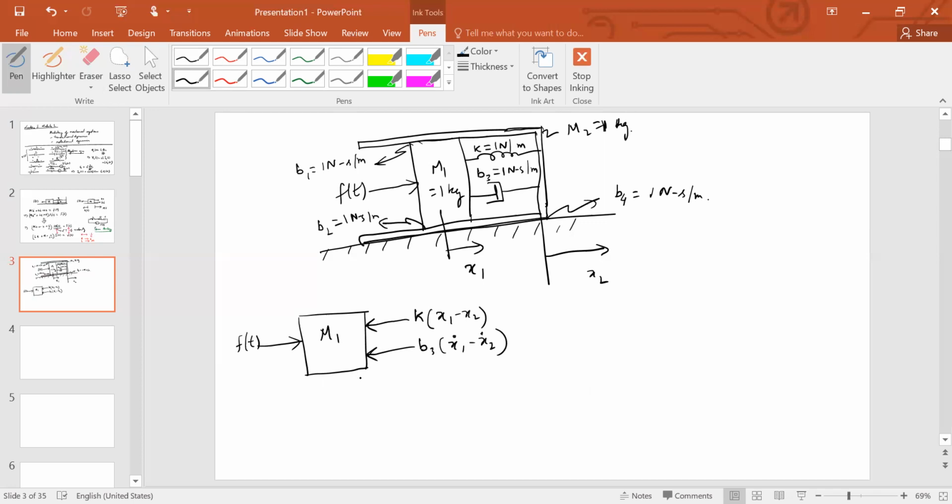All right. Similarly, here also, you see this motion x1. So both these B2 and B1, they also apply forces that are proportional to, here B1 (x1 dot minus x2 dot), here it's B2 (x1 dot minus x2 dot). And then you apply the pseudo force, right? Yeah, you apply the pseudo force in the opposite direction of the actual motion. So that is m x1 double dot. So clearly now equating all of these, the forces to the left and the forces to the right along the x direction, we can write out the equation as